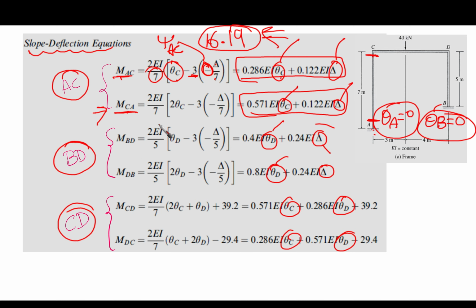Okay, now this is the first equation. This is the second equation. Now let's go to the third equation. The third equation is going to be SAC plus SBD equal to 0. What is SAC and SBD? They are the shear at the bottom of column AC and the shear at the bottom of column BD. They should equal 0 because we do not have any other external forces.